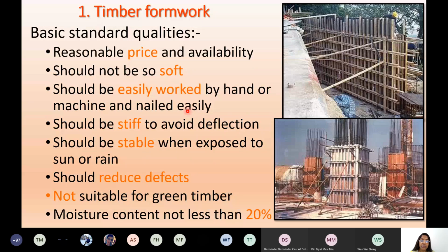When you do the centering, you put the panels together, you cross with the brackets or the screws, nails, all the tools, tying arrangements will be done. So it should be workable at the site. Wood is very easy, you can nail it easily, right? Should be stiff to avoid deflection, right? At the same time, stiff enough to withstand deflection, or mainly wind, right?